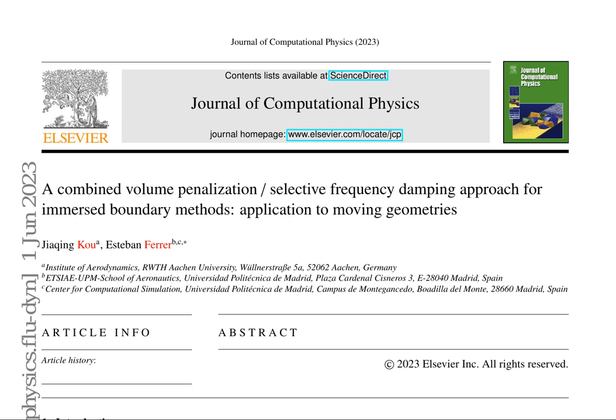To simplify this process, the immersed boundary method (IBM) has been proposed, allowing for the avoidance of body-fitted meshes while accurately resolving complex flows using simple grids. Combinations of high-order methods and IBM have been developed to merge the numerical advantages of high-order methods with ease of mesh generation. For instance, Fidkowski and Darmofal, as well as M. Dias Uller et al., applied the cut cell method to simulate steady compressible flows based on discontinuous Galerkin.